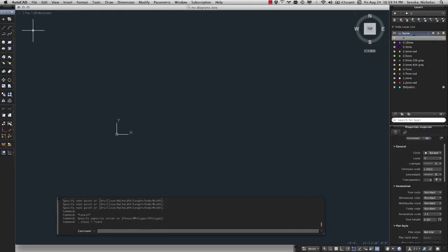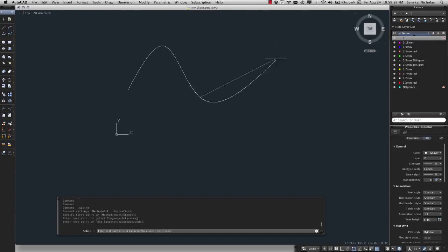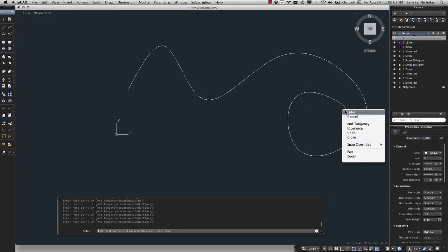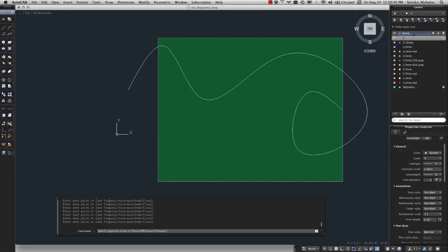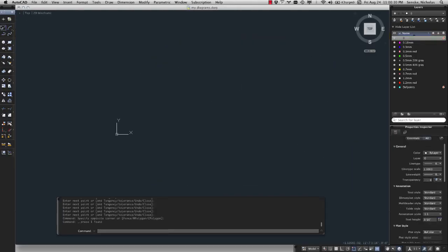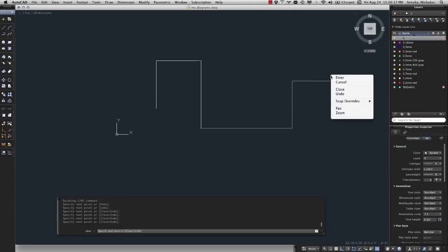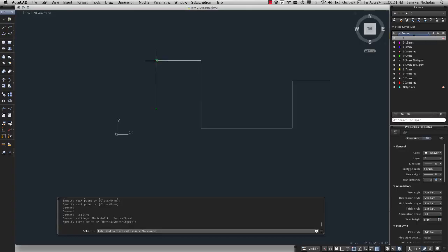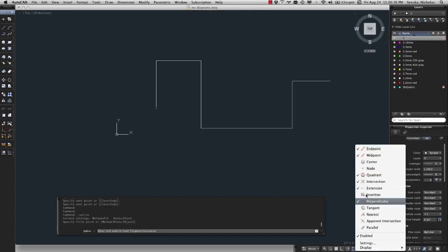Another kind of line that you'd be interested in is a spline. And splines are free-form curves. So you might use this for topo or for strange organic lines that your project requires. I'm going to demonstrate something here with splines. I'm using ortho snap by holding Shift. You take a spline, and I'm using snaps here. It's an object snap, and these are different kinds of snaps.